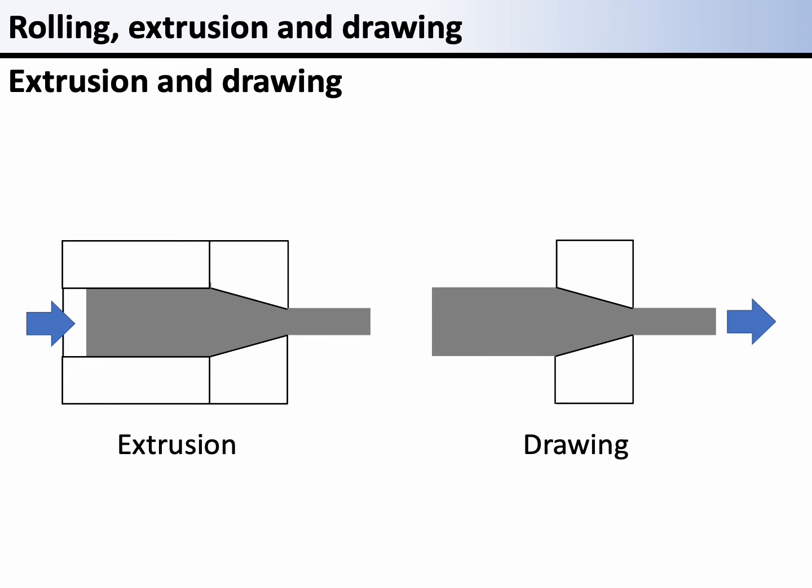Extrusion and drawing are the processes of making longer products by passing material through a die with a hole into the desired cross-sectional shape. For example, rails and frames are made by using this process. They are usually made into standard lengths, such as 2 meters or 4 meters, and the user cuts them from the standard lengths to any required length.